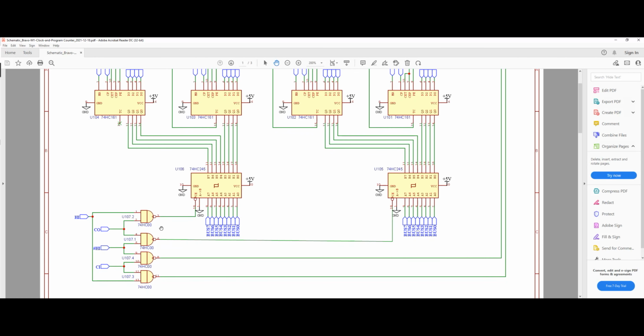So let's see how it works. Let's say that at first, we want to just output the low byte on the bus. By default in our computer, the HI signal is low, meaning that we're not bringing in that high until we want to actually read or write to the high byte. So by default, the HI is low.